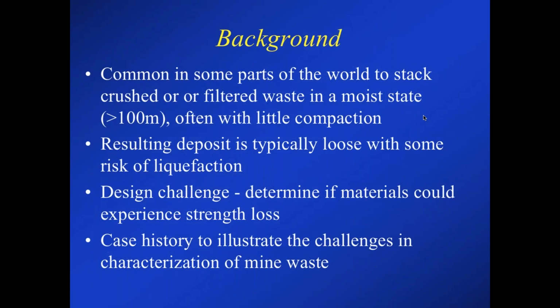The background on this particular project is that it's now becoming more common in parts of the world to stack either crushed or filtered mine waste in a moist state, and these are getting pretty big. They're over 100 meters high in some cases, and the stacking is often done with very little compaction.